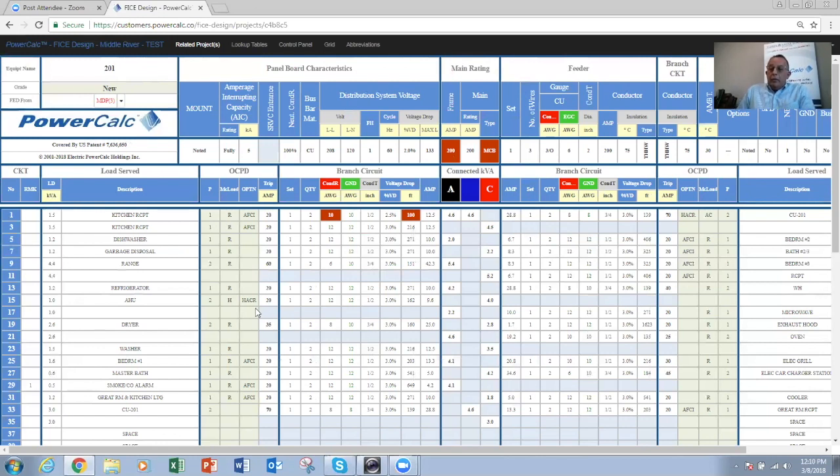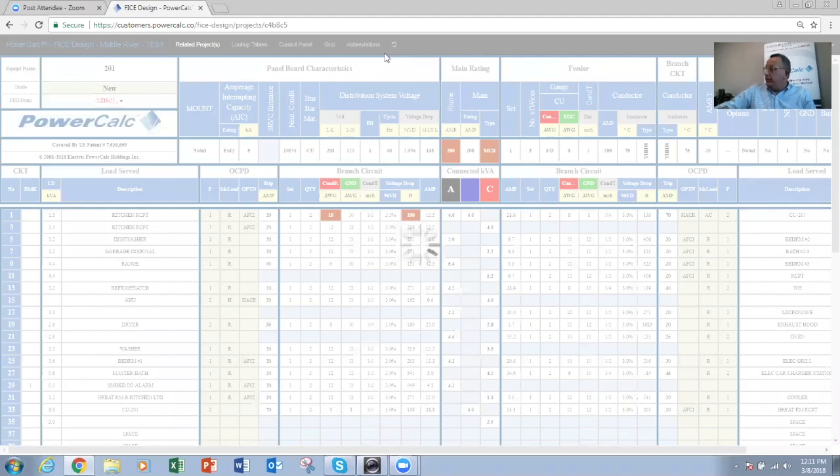So now we loaded the mechanical equipment, and I showed you the building equipment input data sheet. Now, the other part of the air conditioning would be the air handling unit. Again, you can do it the same way by going into building equipment, or you can actually do it directly on the panel. So again, to show you the variety and the flexibility of the system, I indicated in here that it is shown or input the value directly on the panel schedule. So it's air handling unit number 1, and so we show you how it's done.